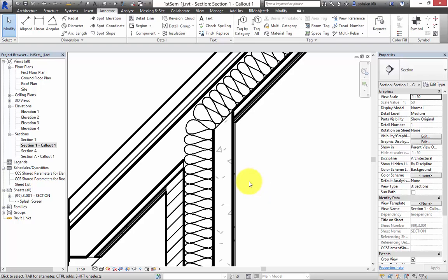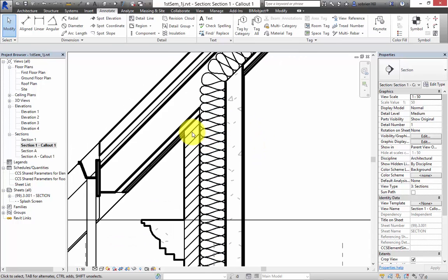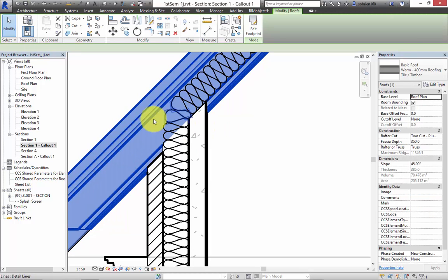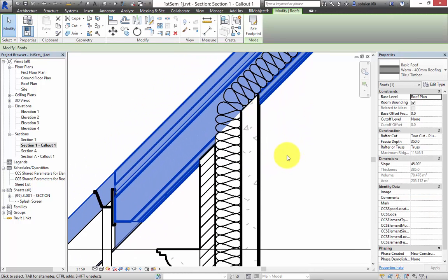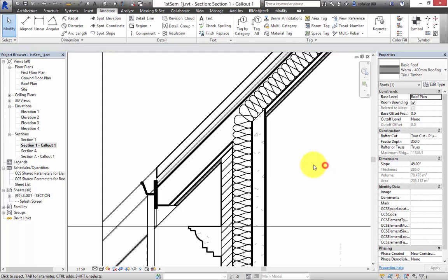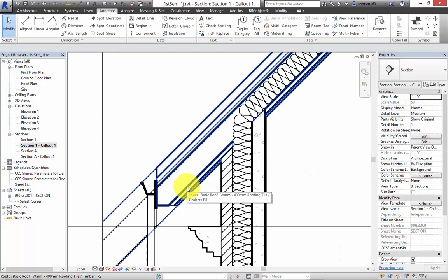believable construction details. The other thing we have here is, because these Revit roofs are made with all the layers all the way through, it's actually taking the layers of plasterboard externally outside the house, which would never happen in reality. But this is one of those things that you don't change in the model, you change in 2D, because it doesn't make any difference to the calculation of the costs in reality.